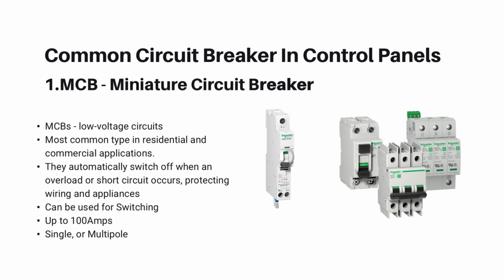If an excessive amount of current passes through a cable, this cable will eventually heat up and cause a fire. Thus, the overheating properties of an MCB are used to prevent the fire. However, the overheat reaction is not instant. It can take a few seconds. Overcurrent is when there is a short circuit and a massive amount of current flows. The circuit will trip and stop this overcurrent to protect our devices and equipment.